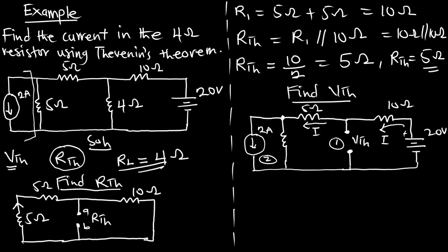And this current is still the I current. Now, when it gets to this junction, it is going to split. This part, we already have it as 2 amperes, meaning if current I is coming and it splits into two, one is 2 amperes, then the current across this 5 ohm resistor is going to be I minus 2. Is that right? Yes. So our current passing through this part will be I minus 2, because the I is splitting. By KCL, current leaving should be equal to current entering. So the current will be I minus 2.